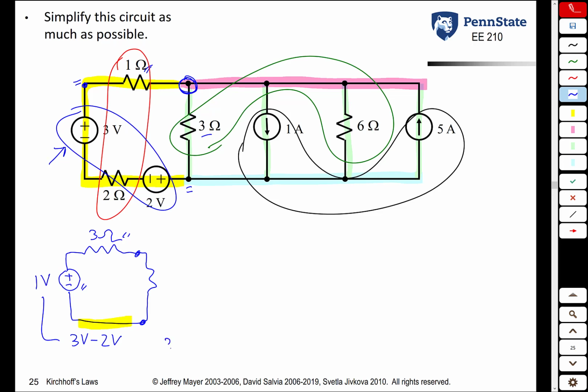Its value, 3 ohm in parallel with 6 ohm, is what? 1 over 1/3 plus 1/6, or 3 times 6 over 3 plus 6, or I could recognize the fact that this is R in parallel with R over 2, which is R over 3, or 2 ohms.